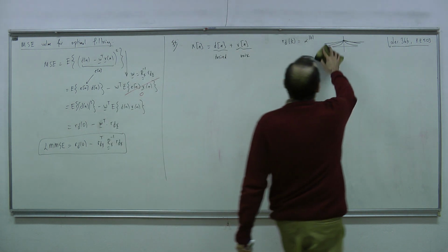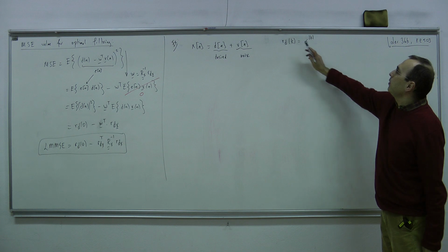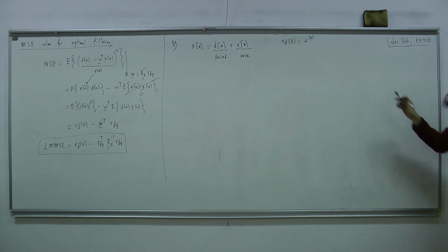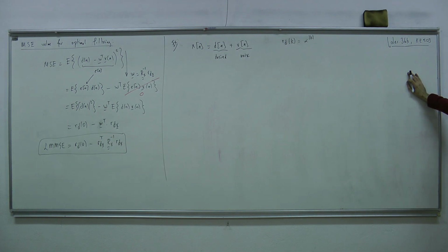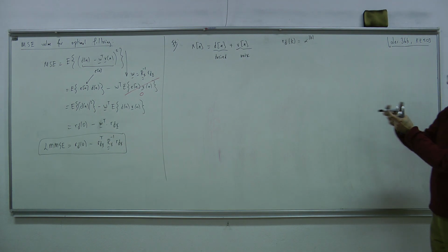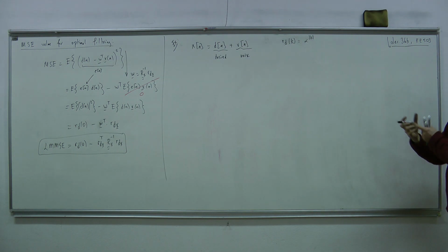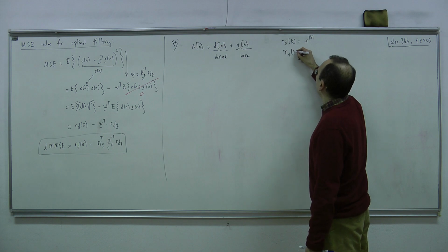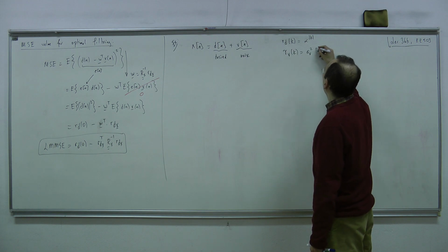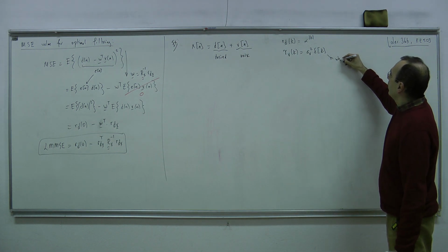Actually, this is nothing but an AR(1) system that we have previously studied. So this signal, if alpha is a positive quantity between 0 and 1, is assumed to be correlated with neighboring samples. How many neighbors? It depends on alpha. I have highly correlated samples in the neighborhood of a sample. About this, Rv(k) is sigma v squared delta[k]. This is even easier. This is what we call white noise, right?